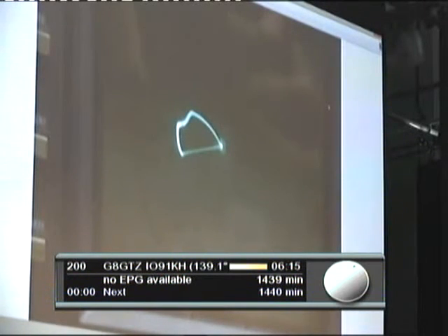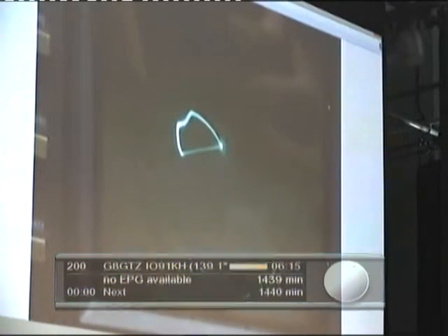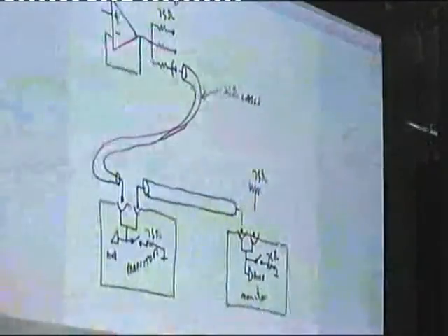Click. And this is what it looked like on the vector scope. It's murdered the burst away completely, and that's what's left of the subcarrier, and you can see clearly that the phase changes. Remember, the phase is a swing this way, so not only has it got diff gain, it's got diff phase. So the result of these errors is that in a viewed picture, the saturation of the colour will change according to its level, and the colour of the colour will also change according to its level. You're onto a hiding to nothing.